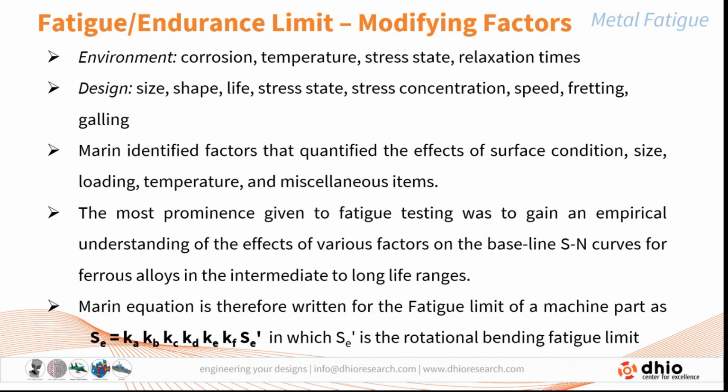So these things should also be taken into account when it comes to the design aspects of the size, the shape, the life, stress state, the stress concentration, and the speed, that is the rate at which the loading occurs. And if there is any friction between the parts, those things are to be taken into account. And these factors are to be incorporated into the behavior of the material.